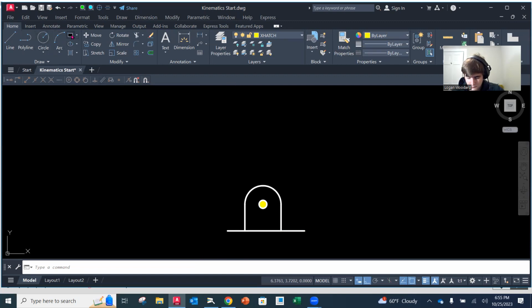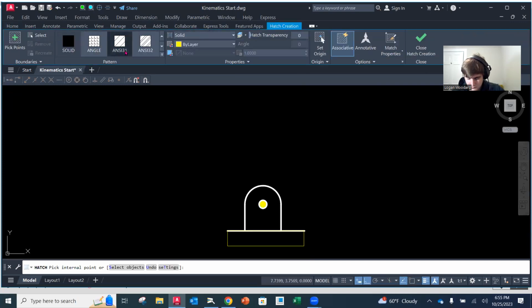All right, so I'm going to do a corner rectangle. I'm going to go down and kind of go over here-ish, about that far. So I'm just going to create a rectangle that I'm now going to do a hatching in, but this time I'm not going to do solid. I'm going to do ANSI 131. This one has the separations at an angle, and then I'm going to go down in there and just kind of judge that spacing.